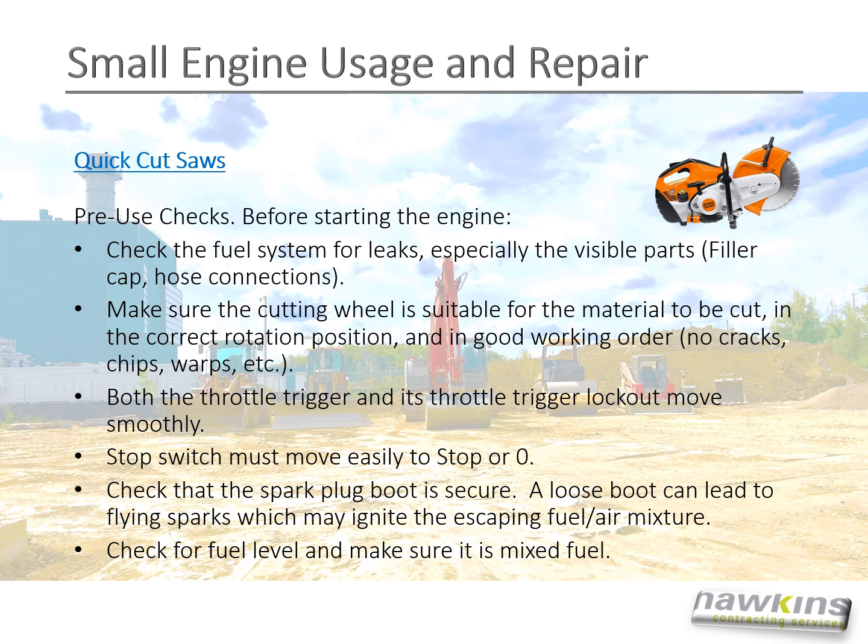Check that the spark plug boot is secure. A loose boot can lead to flying sparks which may ignite the escaping fuel air mixture. Check for fuel level and make sure it is mixed fuel.